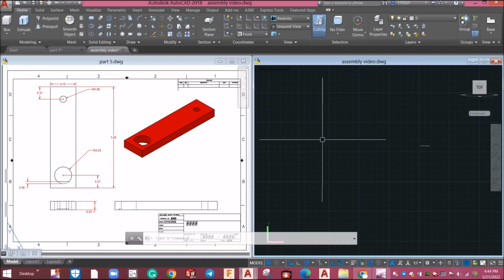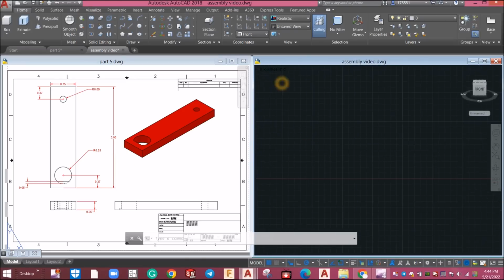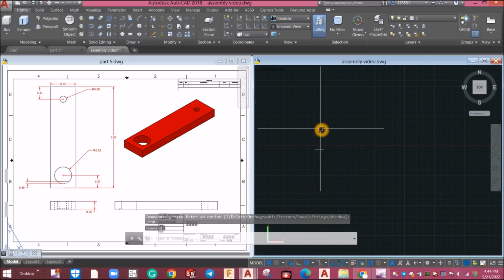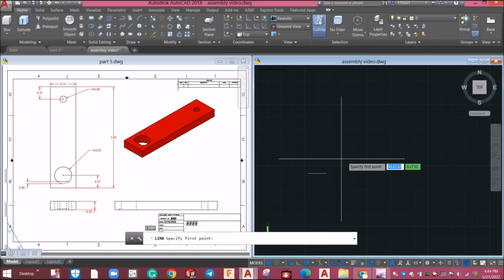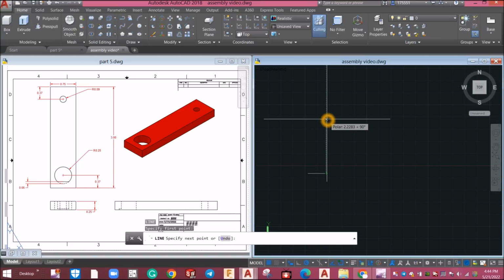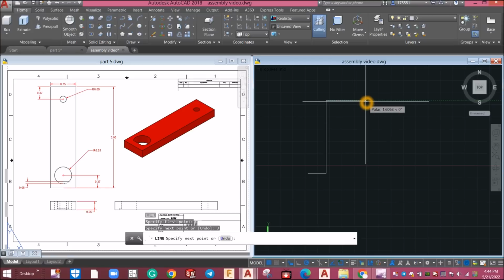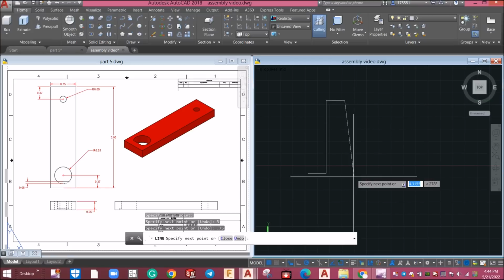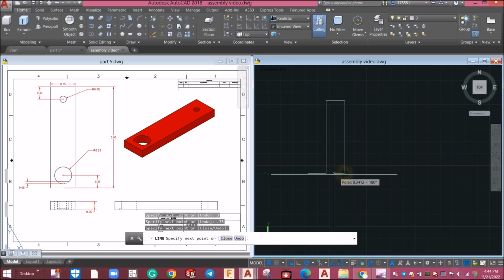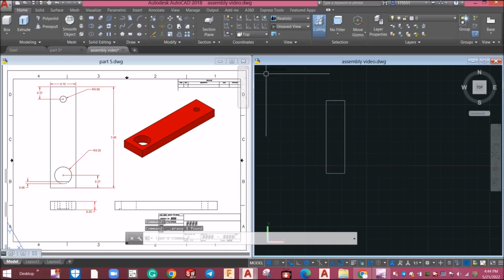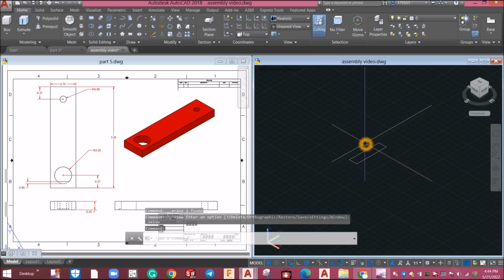This time I'm gonna draw my object from top view. So click this one, select top, and I'm gonna start with line from this endpoint upward for 3 units. Then the width is 0.75. I'm just gonna track and close. Delete that. I'm gonna bring my drawing to southeast isometric, join the segments,